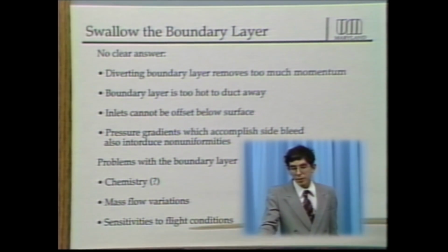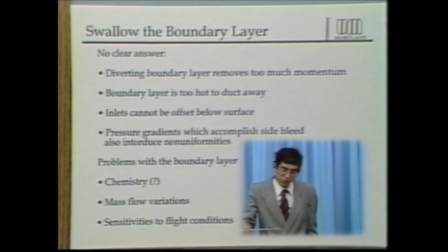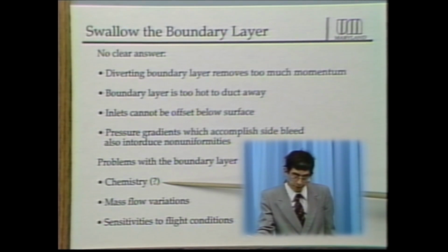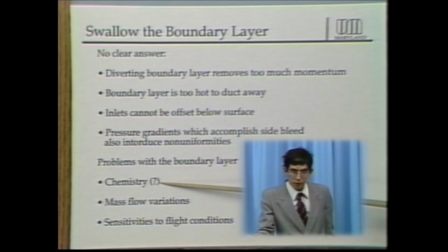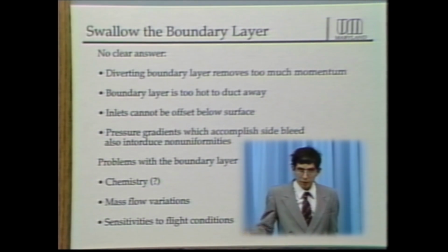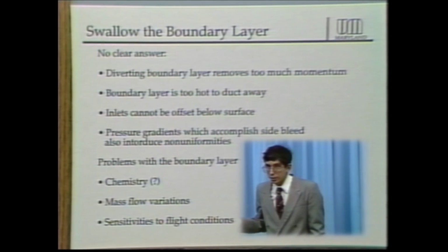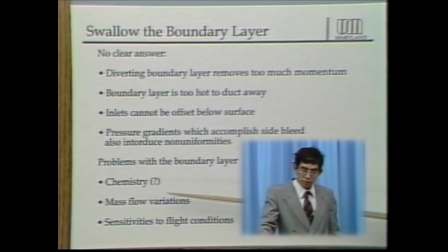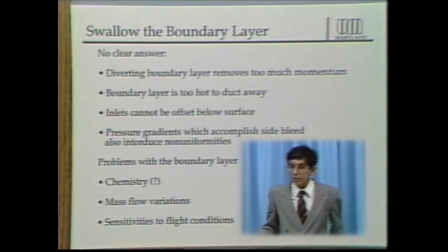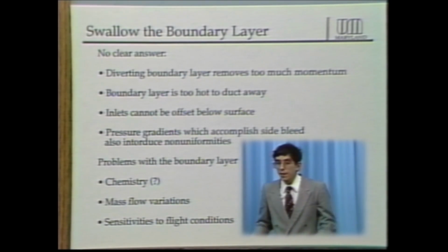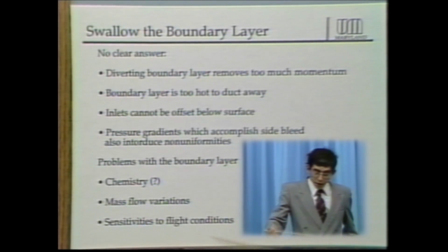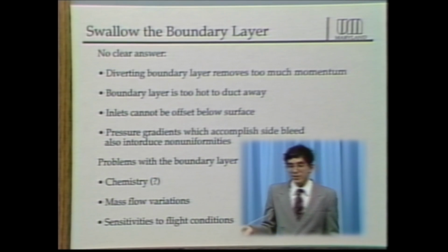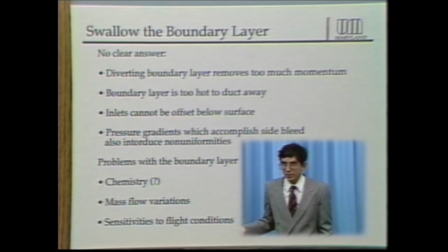If we don't know what state the boundary layer is in, laminar or turbulent, that also figures into whether we can get combustion in the boundary layer. We don't even know how the chemistry in the boundary layer couples in to the turbulence of the boundary layer. In fact, that's a real hot research question right now. How does the chemistry of a turbulent flow affect the level of turbulence, and how does the level of turbulence affect the chemistry? That's a big unknown. That's also a commercial advertisement for an area that we need more work in.